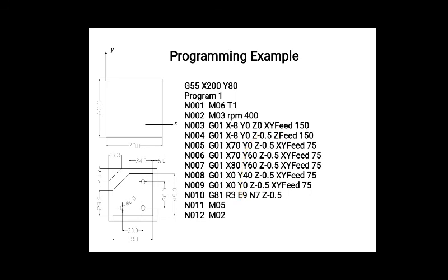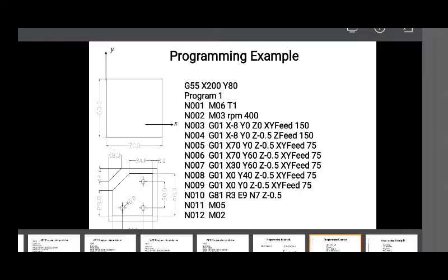And the third one is system shutdown. Here you can see we turn the spindle off, and the end of block or program stop is used in system shutdown. So in part programming there are three main parts: program setup initially, in the middle the chip removal, and the last one is system shutdown.